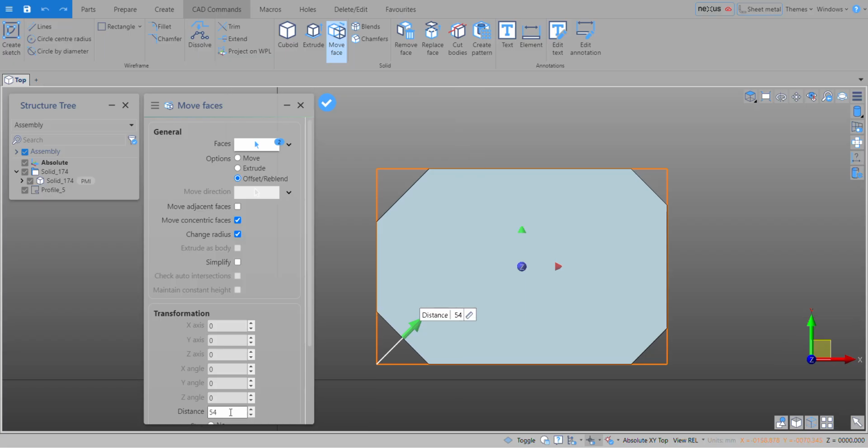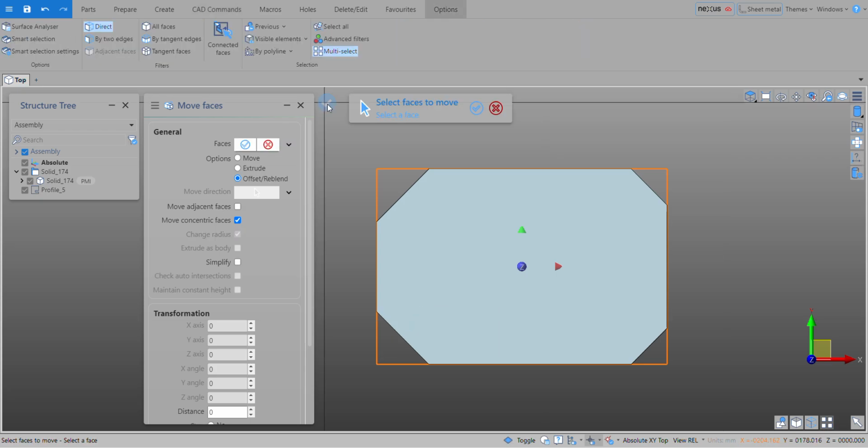here or you can fill it in here, but notice I'm dragging left to right, not right to left. It makes a big impact because I'm only picking up those corners that I'm dragging over. Rather than if I come the other direction, I'm picking up the whole profile, and you can test that and see the impact. And we can accept that.